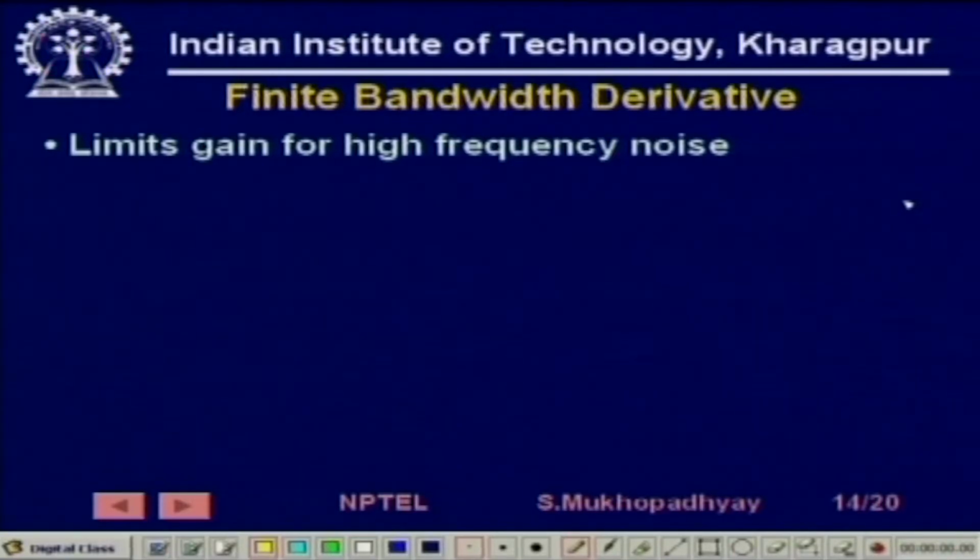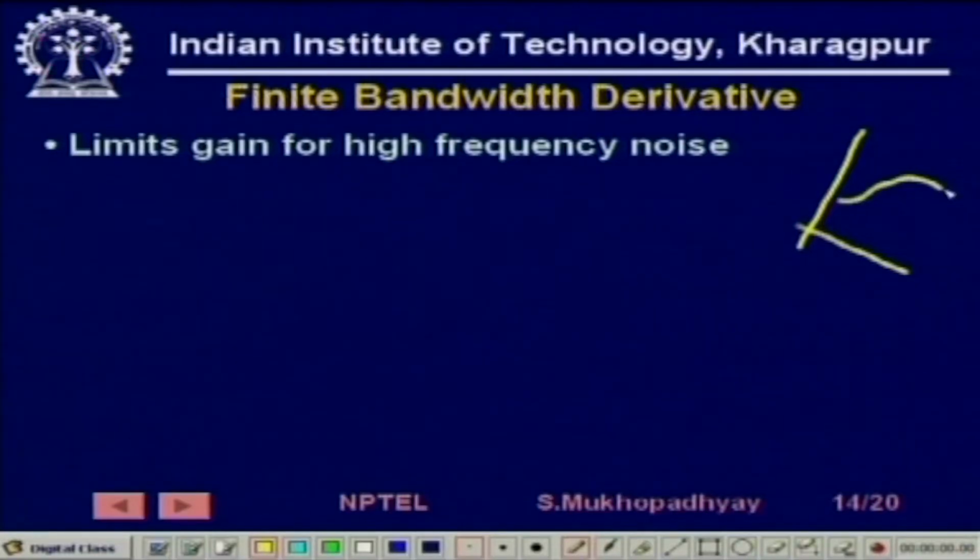Flow sensor, flow is always turbulent. So the fluid actually flows in random fashions. Whenever you have a flow beyond a certain velocity, flow is turbulent. So whatever the sensor, the turbulence induces frequencies which are much higher than the average volumetric flow rate. While the average volumetric flow rate may be varying like this, the signal that you will get from the sensor may induce very high frequency components. These signals are actually due to the turbulence. So this gives a noise, right.